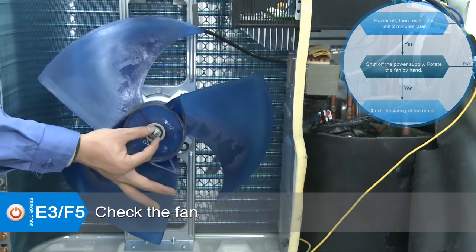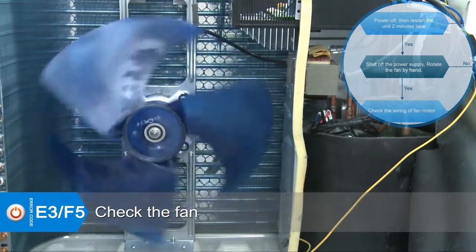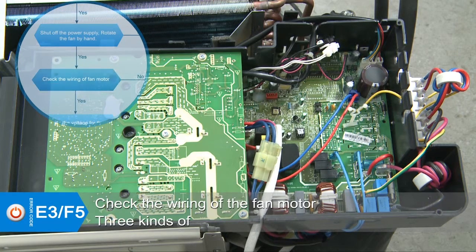Rotate the fan by hand. Check whether the fan is blocked or rotating normally, and whether the screws which fix the fan have been tightened enough. If the fan is normal, check the wiring of the fan motor according to the wiring diagram. Commonly, there are 3 kinds of DC fan motors with different pins.